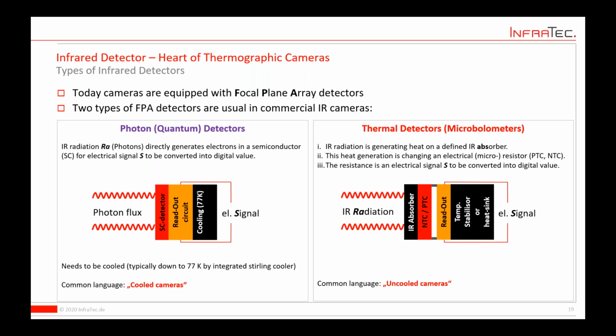They work in a way that the pixels adapt to the IR radiation by changing their temperature itself, and this temperature change is converted into a change in electrical resistance. You can then analyze this change in resistance and convert it to an electrical signal, which corresponds to the IR radiation, giving you after the calibration and reading in a DC value or whatever.